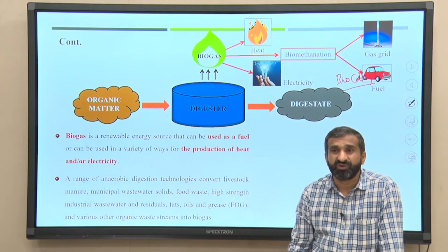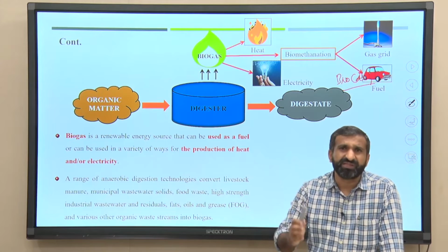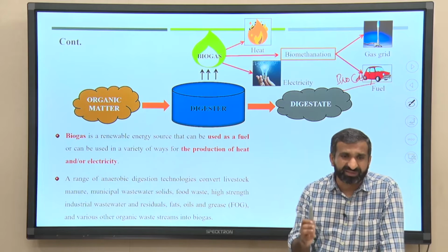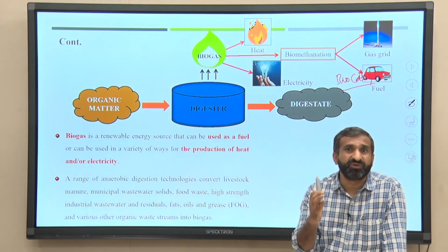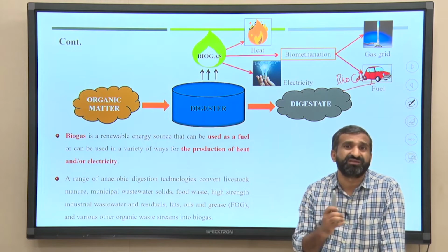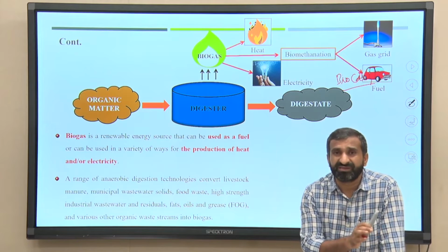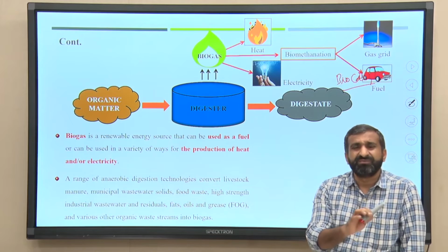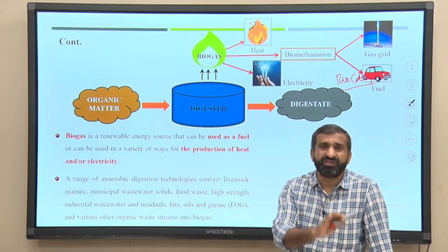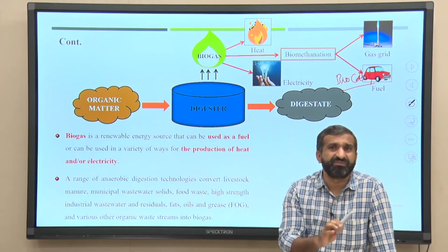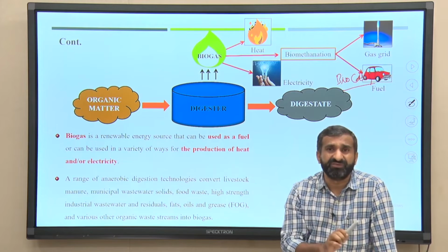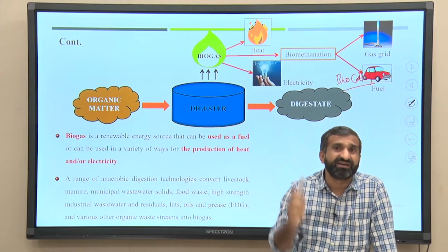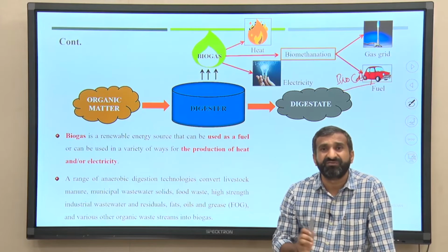So, low sludge production is the major benefit of the anaerobic digestion process, and anaerobic digestion can also take high BOD5 wastewater. In an aerobic system for wastewater or sewage treatment we can go up to 200-300 milligram per liter BOD5, but in the anaerobic system we can go up to 700-800 milligram per liter BOD5 value.